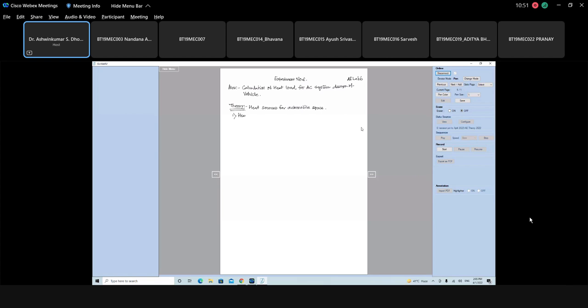So heat flow from exterior walls, this including solar radiation. So the formula, and please note that for calculation of the heat load, we assume the steady state condition. We are not assuming any transient, because in transient, then that analysis will become further complicated.